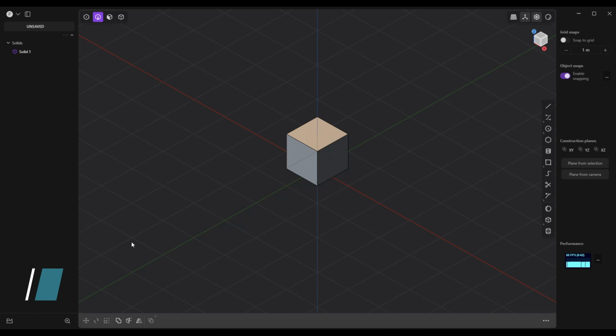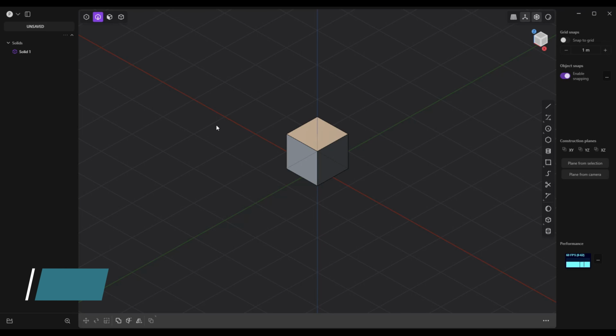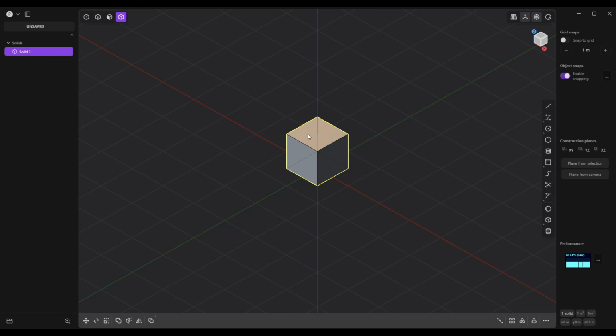My name is Mike and today we are going to be modeling a YouTube play button, right? So let's get rid of our default cube first. We're going to go to object mode, click on it, and hit delete, there you go. And then we're going to start with the outer perimeter of the play button sign, if you will, okay?